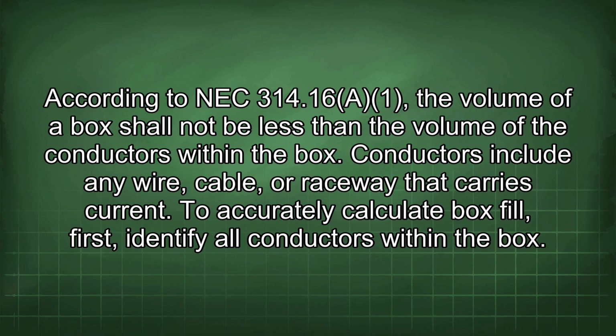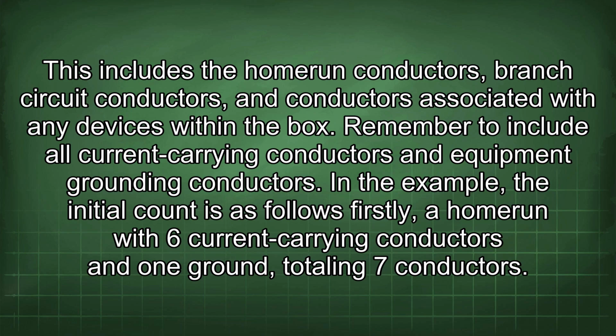To accurately calculate box fill, first, identify all conductors within the box. This includes the home run conductors, branch circuit conductors, and conductors associated with any devices within the box. Remember to include all current carrying conductors and equipment grounding conductors.